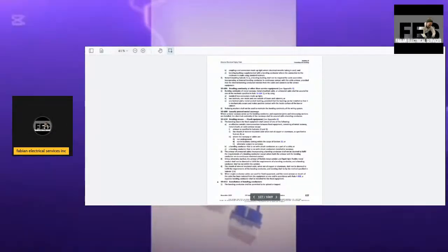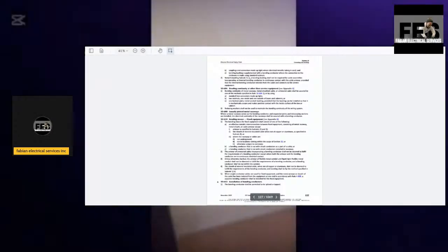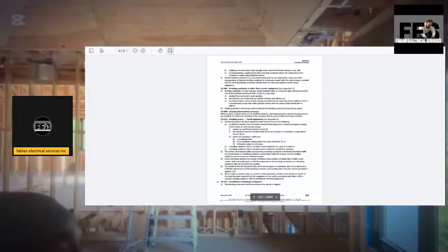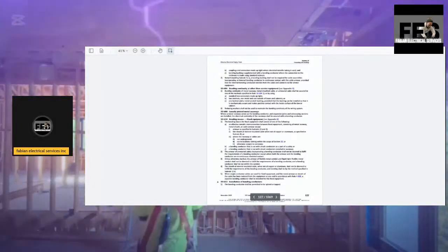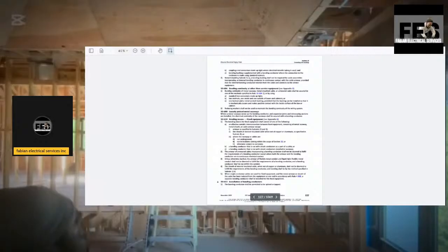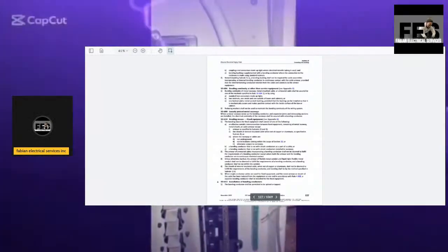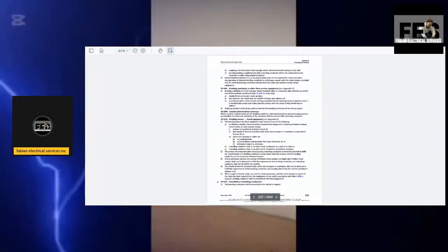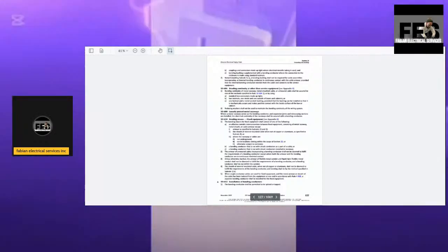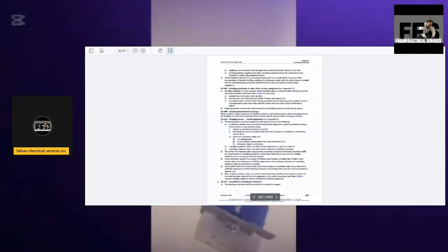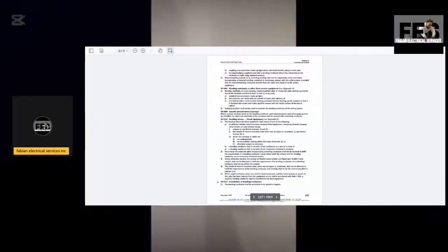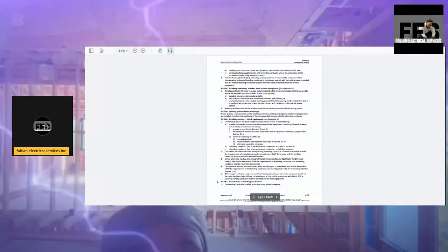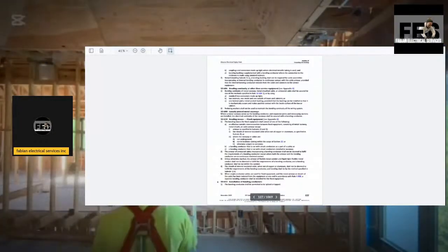Where a metal raceway serves as the bonding conductor and expansion joints and telescoping sections are installed, the electrical continuity of the raceway shall be assured with a bonding conductor. Bonding means for fixed equipment: the bonding means for fixed equipment shall consist of one of the following: an effective metallic interconnection between fixed equipment consisting of metal raceways, metal sheath, or cable armor, except armor as specified in Subrule 2-3, or the sheath of mineral insulated cable when not of copper or aluminum as specified in Subrule 4.